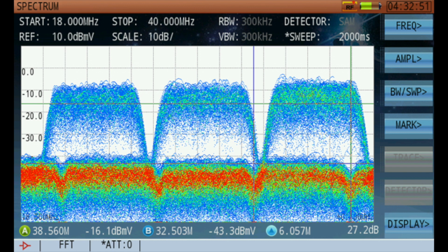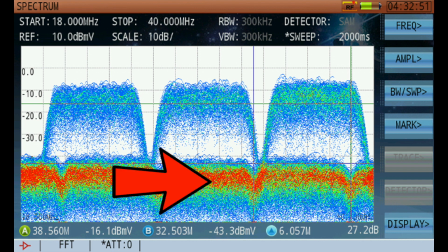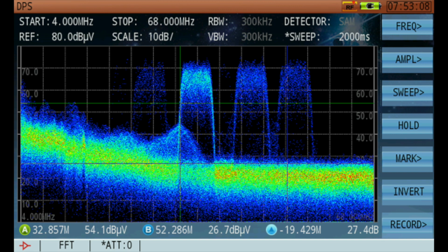More signal presence at a given bitmap location will signify heavier RF density over that bitmap screen location, hence hotter or redder in this case. But when less signal presence is captured during the acquisition period, the bitmap will be cooler, or bluer in this case.